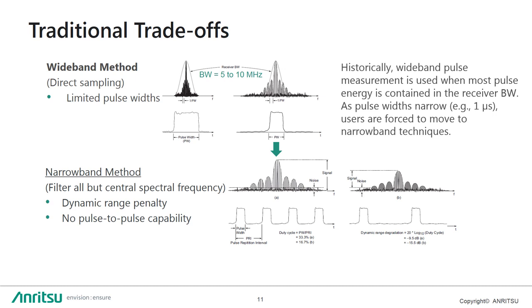The lower limit is primarily limited by the overall system IF bandwidth and associated aliasing avoidance, while the profiling measurement resolution is limited by the receiver gating capability.